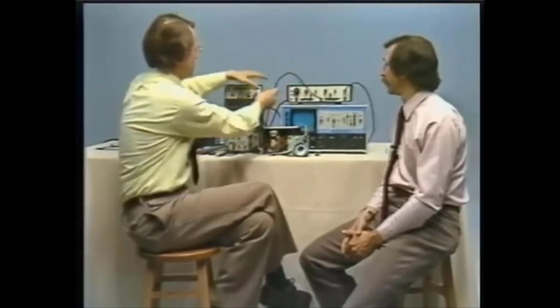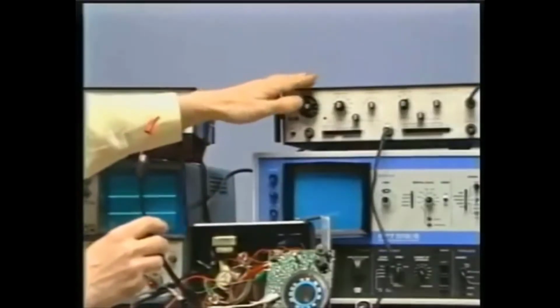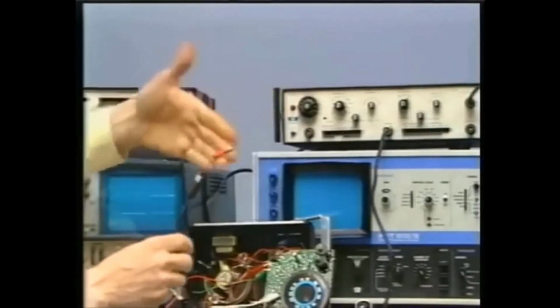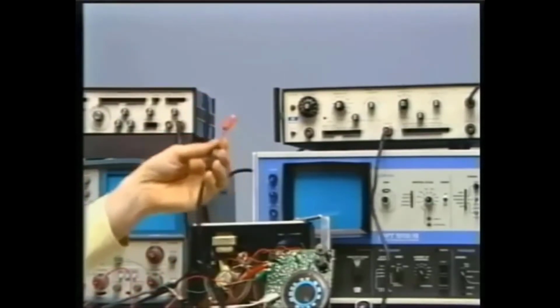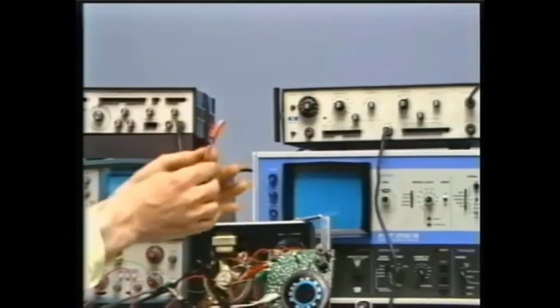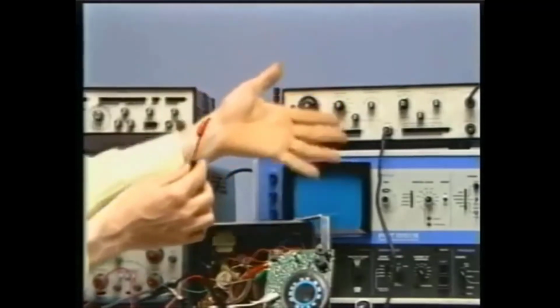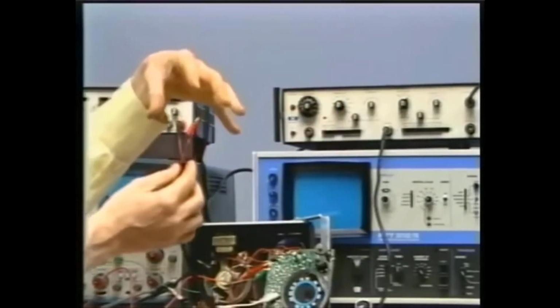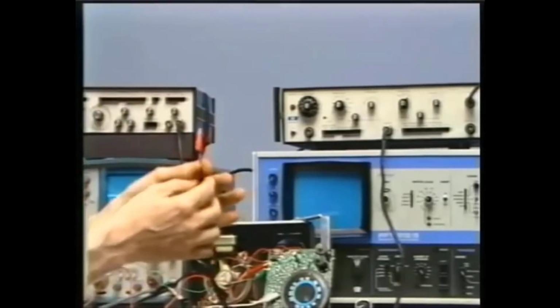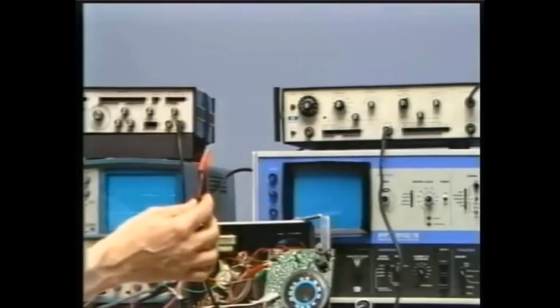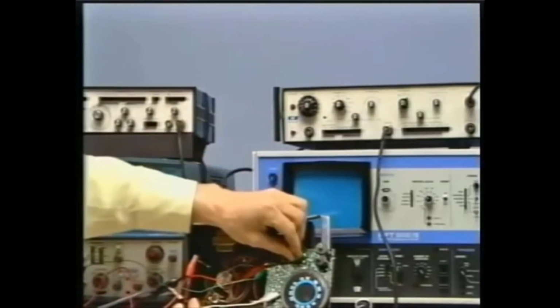What we're going to do then is use the audio oscillator along with the amplitude modulator, and we're going to take from the output now the lead here, and this will act as the antenna. This device was not designed to put out a lot of power, but fortunately we don't have a lot of distance to go over. What I'm going to do is turn myself into an antenna. I'm basically 150 pounds of salt water, and when I touch this, the signal coming in here, which is radiating a little from the wire, is going to suddenly radiate from my whole body, and hopefully will be enough to be picked up. So what I'll do is I'm going to turn this on.